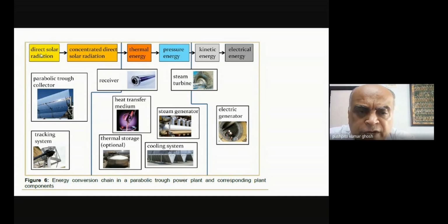One is diffuse radiation, which means that the solar radiation got scattered by dust, dirt, moisture in the atmosphere, and it became diffuse and lost its beam-like property. The other part is the portion which did not get scattered, which is what we call direct solar radiation. Only that part you can concentrate. You cannot concentrate diffuse solar radiation.